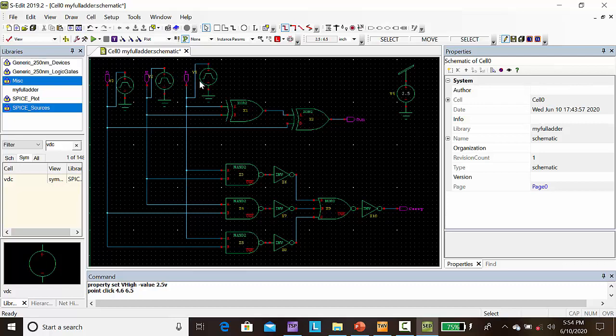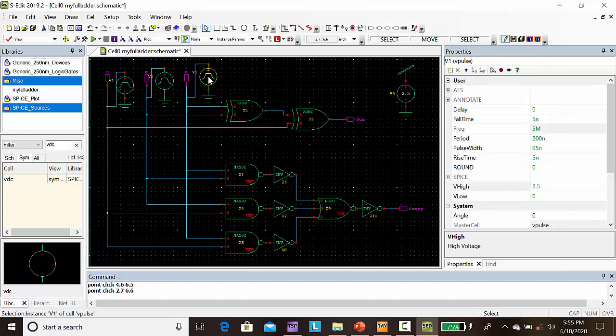Next, to input all the combinations we have to provide 0 0 0, 0 0 1, 0 1 0, etc., up to 1 1 1. For that we have to make some alternate arrangement in the pulse. So if you click the first pulse, we can give the pulse period, make it as 100. So alternatively this pulse will automatically change. Second pulse we can make it as 200. By default it is 200 only. Let it be there. No need to change anything.